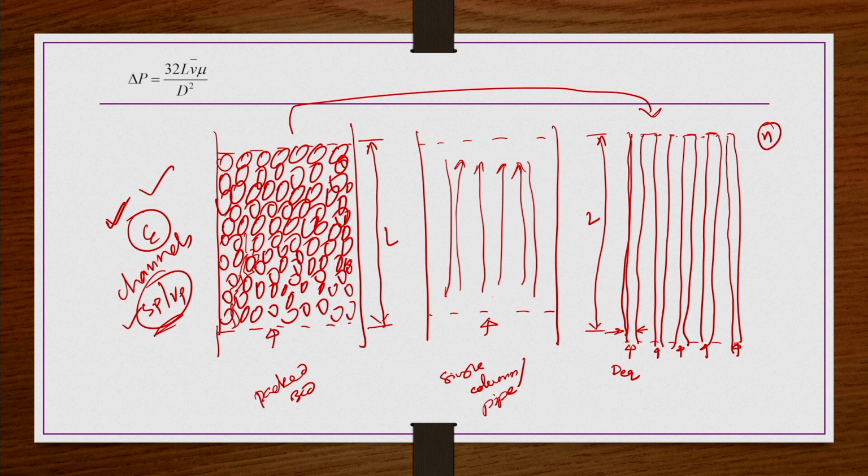So, we are replacing the bed with n number of capillaries having the same height as the packed bed height, right. Those n capillaries form a bunch of capillaries and allow the fluid to flow through. Then whatever void space is available in this bunch of capillaries is equal to the void space of the packed bed, that epsilon that we have taken, such that n should be decided. Should it be 10, 100, 1000, we do not know, indeed we do not want to know at all. But theoretically this is the one representation that we are doing.